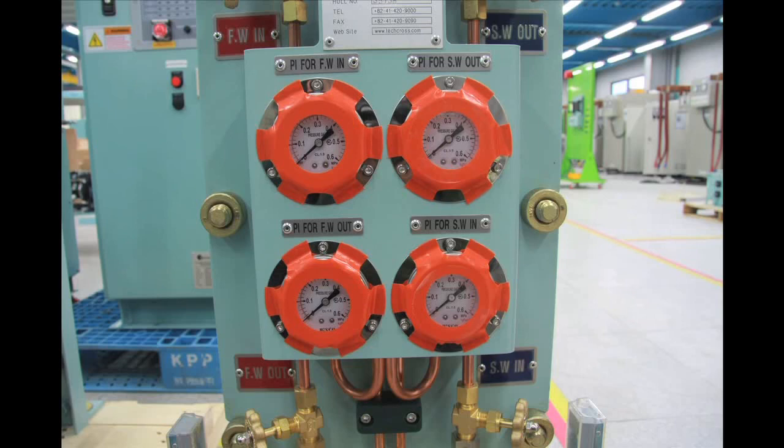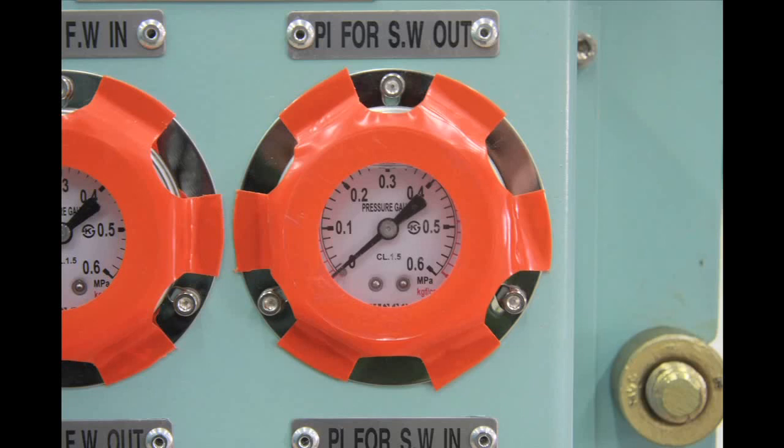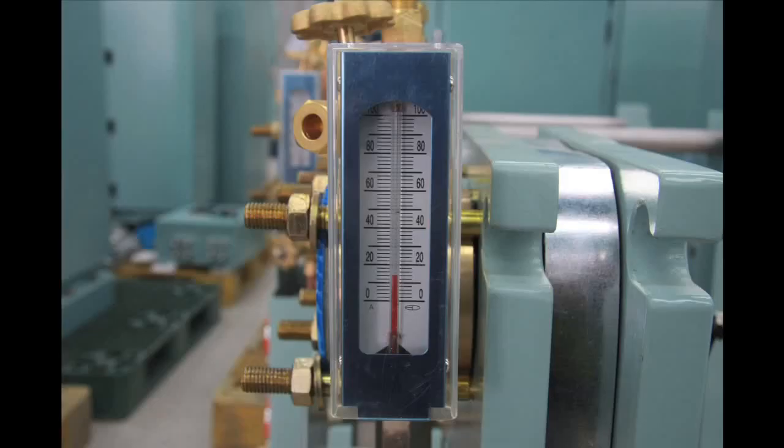Check if there is any problem with circulation of seawater in cooling water, which can be caused by foreign materials in the HEU, through a pressure gauge and a thermometer installed in HEU. Check if the pressure gauge installed in both inlet and outlet of seawater and freshwater, cooling water, shows pressure of seawater and freshwater properly. If the temperature of freshwater cooling water is over 40, check the temperature of seawater. Check that HEU shows the temperature of circulating seawater and freshwater properly.